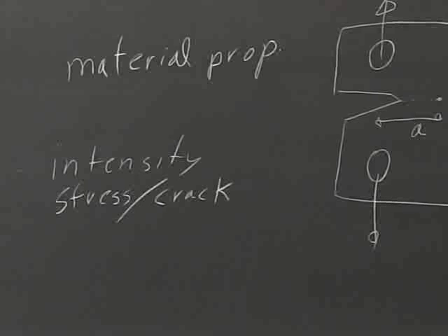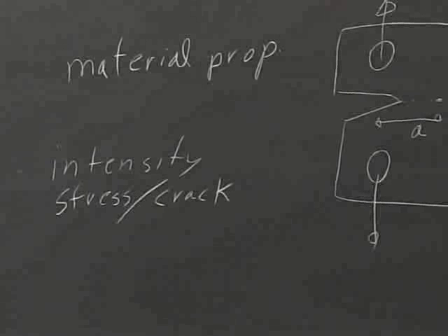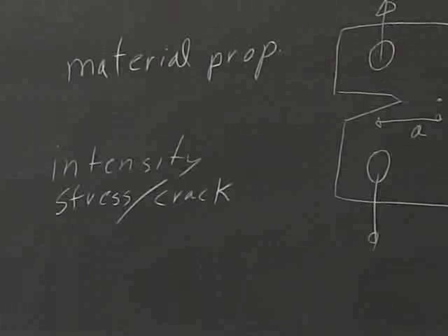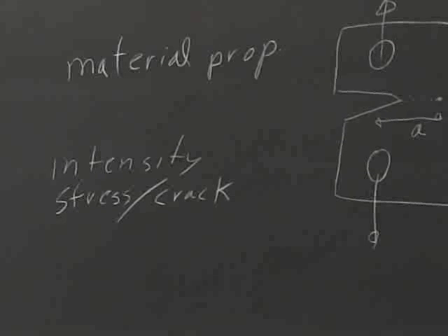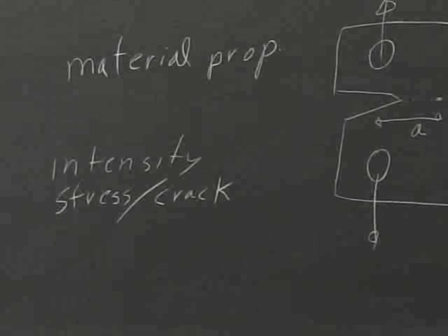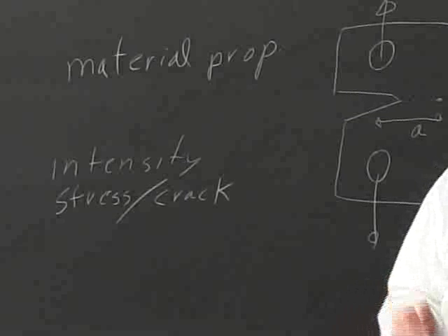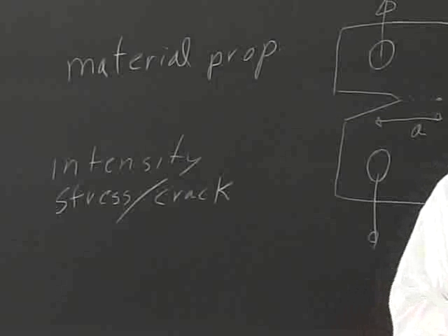For metals, normally the frequency doesn't matter as much. For polymers, it can play a role as well. And if you're doing stress cracking, or stress fatigue corrosion, then obviously it will matter what the loading rate is and everything. So it's a little effort, if you're going to say, I'm going to do this type of analysis, to make sure you have appropriate data.